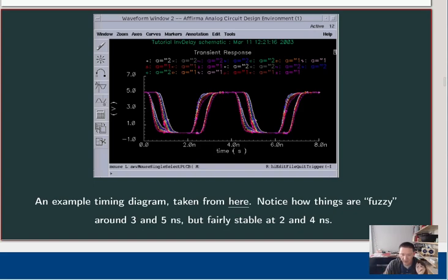So here's where I think this might make sense. This is a timing diagram for a chip. You can think of this however you want, but essentially there's some input going to a chip, a gate of some sort. It's going to then respond and then show its output. So our abstraction has been that a NOT gate, if we set an input of 0, the output is 1. And so we set 0, we read the 1. We set a 1, we read the 0.